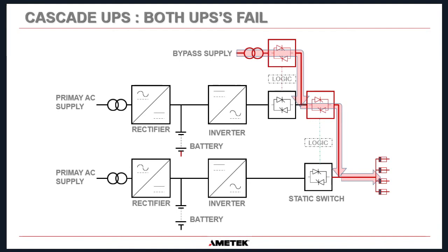A lot of people complain in this situation that UPS-B, the slave UPS, is never going to be supplying load and therefore you can't rely on it. I believe that if you do the correct maintenance once a year, you are going to switch to the slave UPS while maintenance is being performed. And with the technology we have these days, whether the system is loaded or not, they are very, very reliable. But that's just my opinion. Everybody else has their opinion.